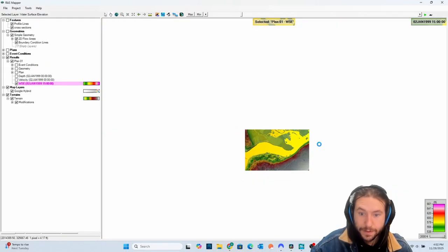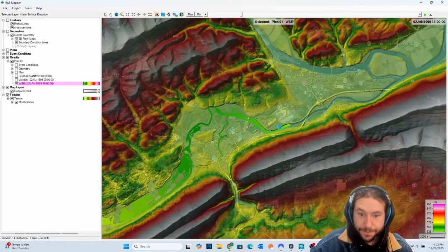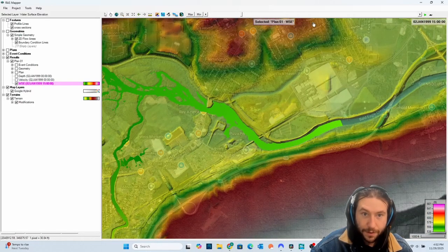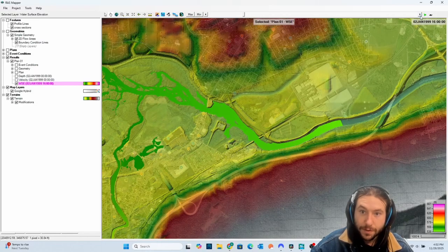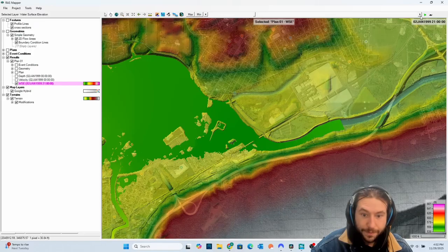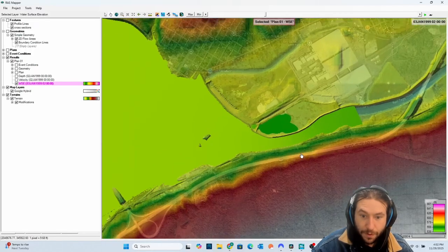Let's go down and look at our levee down here. So it looks like our levee's still doing all right. Our flood wave hasn't gotten all the way down here yet. So let's go ahead and tick forward. You can see again, we're filling up more directionally. And our levee fills almost all the way up, but still spills over right here.